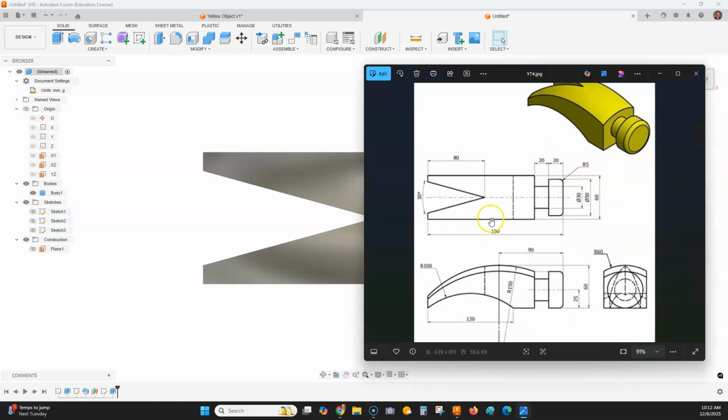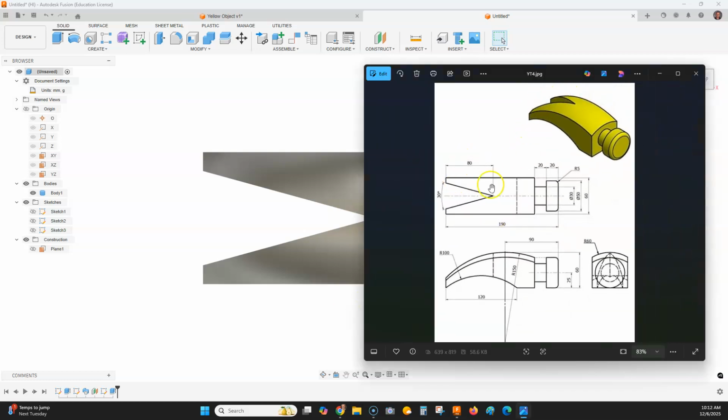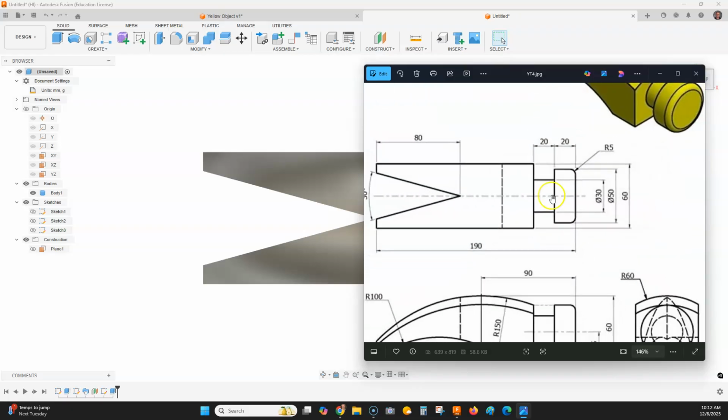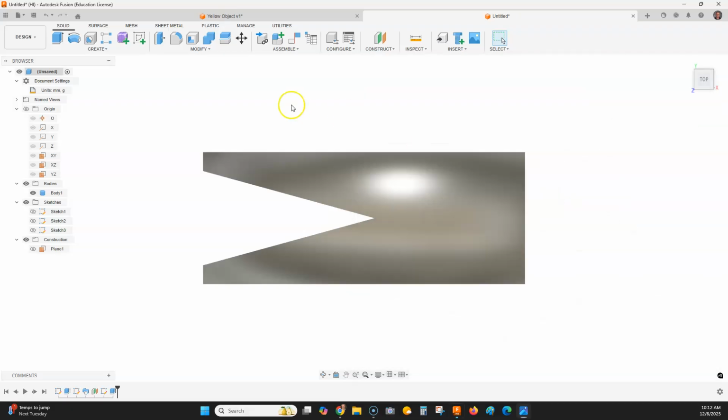Let's go back to our drawing. Take a look here. We have our cut in the top. That's a nice cut. We made that curvature first. That curvature always looks kind of cool. So where we're at next, I want to create for myself this little nub coming out, whatever you want to call it, and that is a diameter of 30 and a distance out of 20.